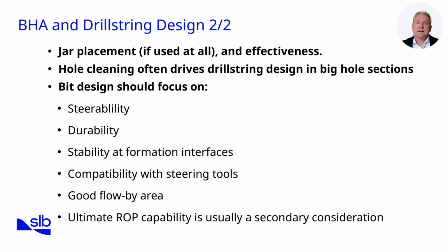In ERD, a steady, controllable bit is preferable to a fast one that causes vibration or trajectory control issues. Ultimately, ROP is a secondary consideration in ERD. The priority is staying in hole longer, maintaining trajectory control, and ensuring cuttings transport efficiency. The overall drill string must balance lightweight for reduced drag with robustness for long, challenging runs.